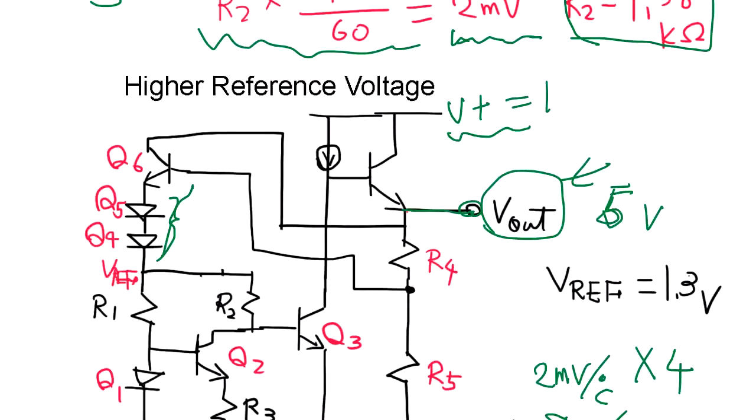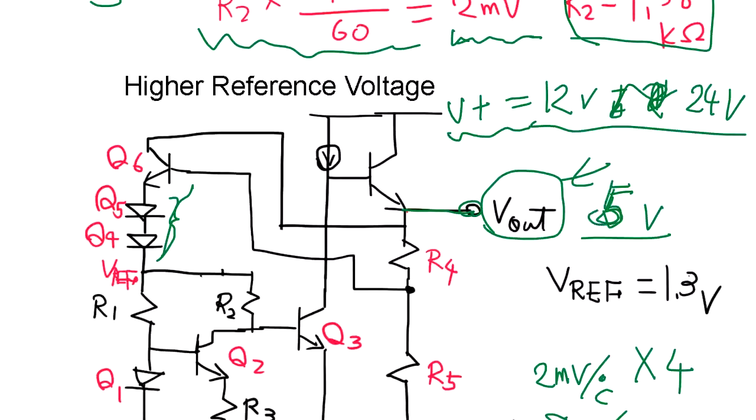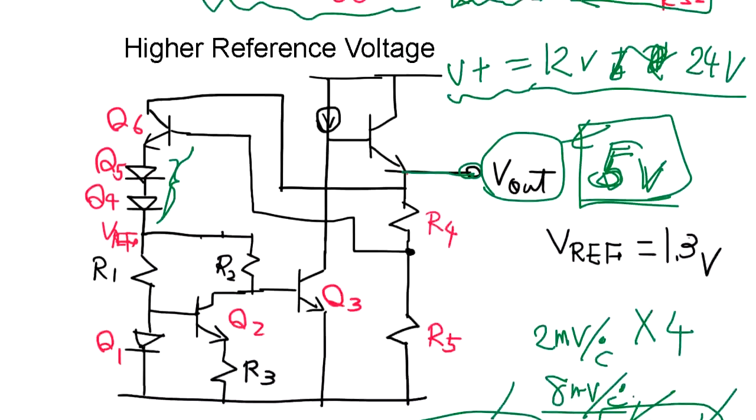This is like a 12 volt plus minus, even, you know, 12 volts to 24 volt, doesn't matter. You still get constant about 5 volt, you can get that. Okay, so the reason why you take it from the emitter is there is plenty of supply of current through this transistor.